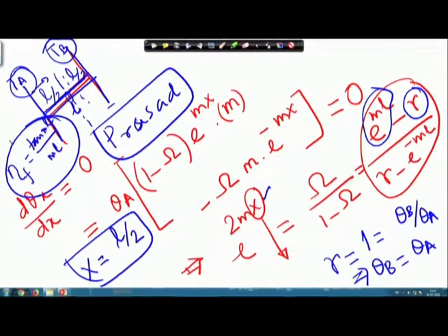That was the fin efficiency, provided we know the exact location of that extremum. But as we have said, this corresponds to a particular situation where half of this fin is attached to this, or half fin idealization as it is called.